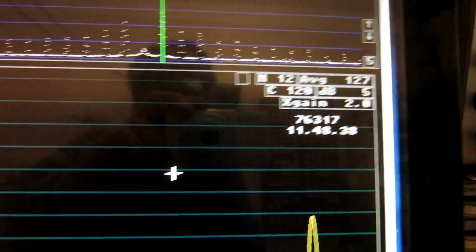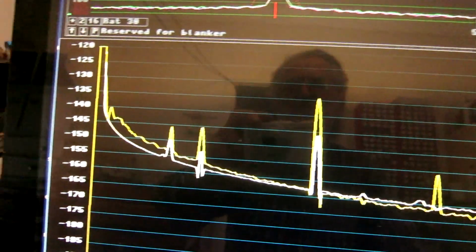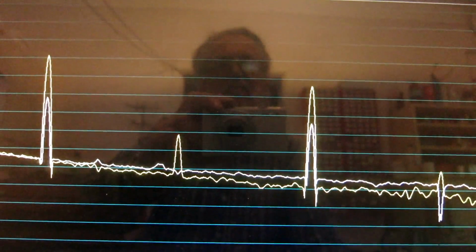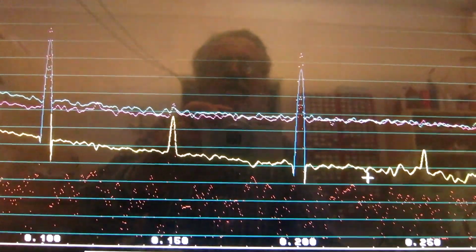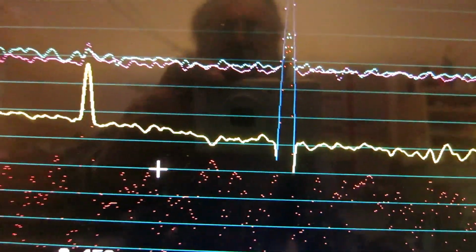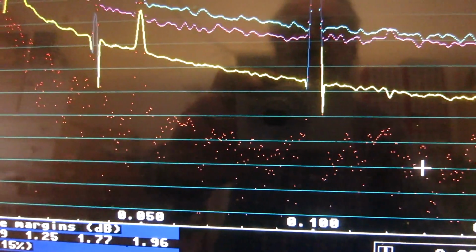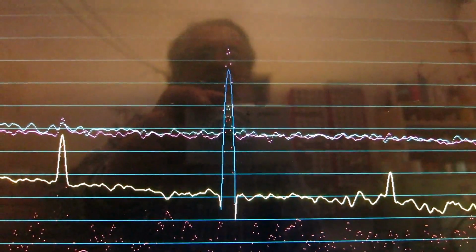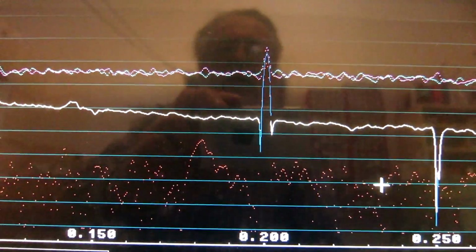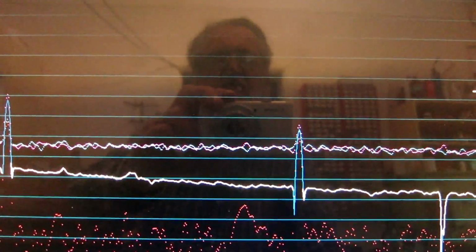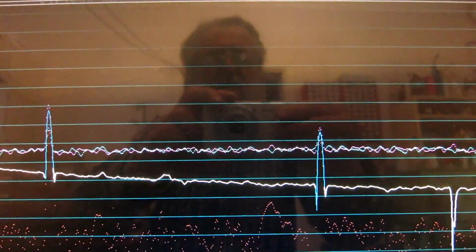11.5 hours. It looks fairly similar, the spectrum I have. I look at the phase noise to see where is the imaginary part, and it's down here. So I get fairly accurate phase noise readings, and then the amplitude noise is even better. So I will save again these images and do evaluation from paper.